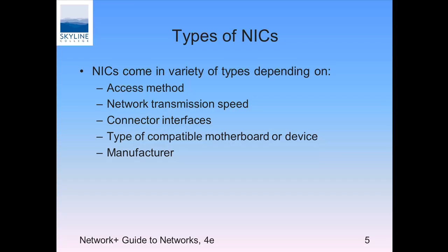When we talk about the devices, I brought these motherboards in so that you can see the slots that we have now. The old slots are on these motherboards that are over here on the wall. You can take a look at those. But these new ones, this one has PCIe, which are going to be the fast ones, and I was just looking at those, and they go from like 500 megabits per second to just a little under 4 gigabytes per second, depending on which ones we have. And these both are PCIe. They go on lanes, a single lane and a 16 lane. So the 16 lane has 16 of the single lane speeds.